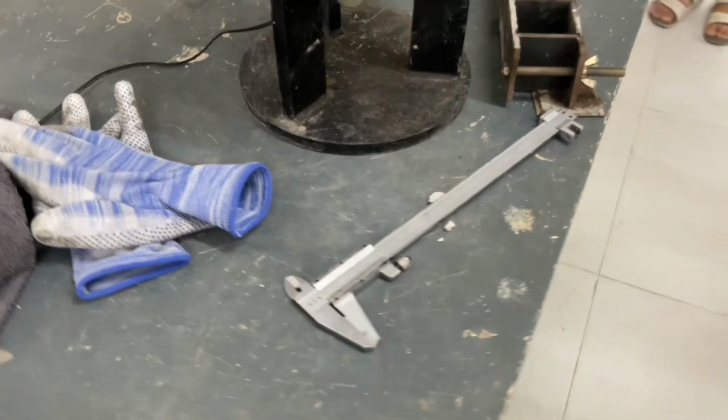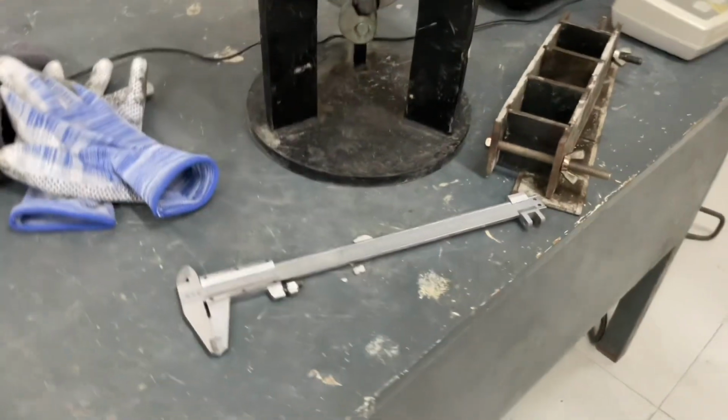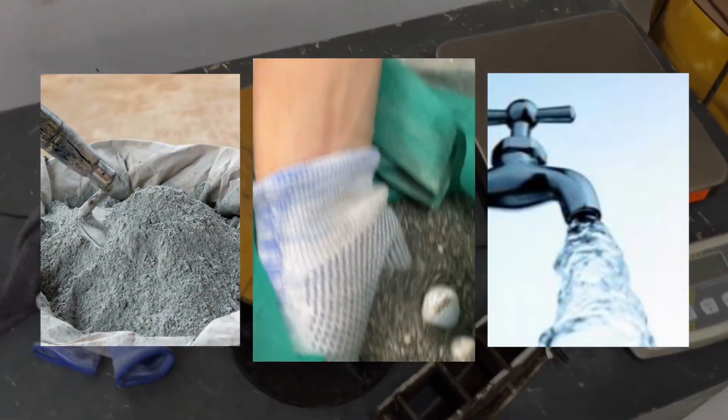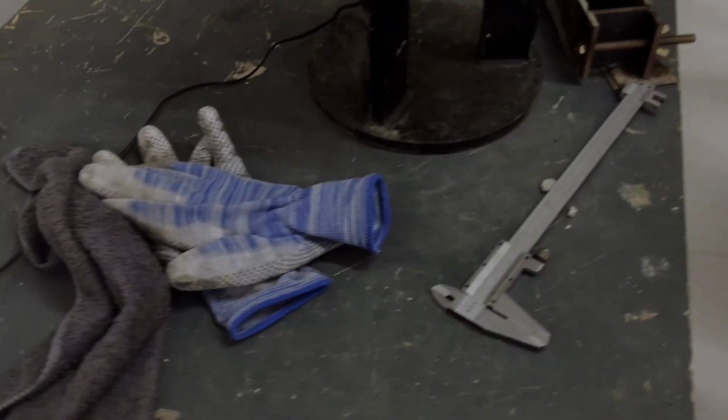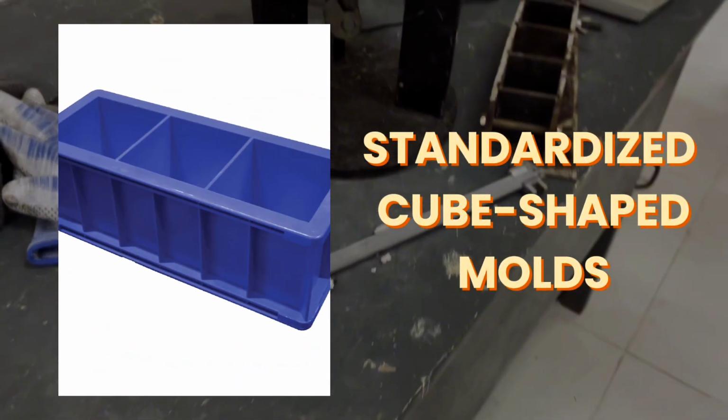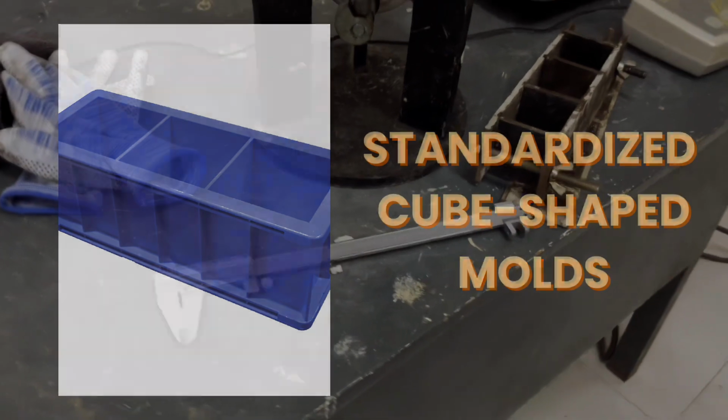Starting the experiment proper, first we gotta gather the things we need. That includes materials and equipment. For materials, we need cement, sand, and some water, which will all be measured as we go through the testing. For equipment, some standardized cube-shaped molds, which is typically 50mm cubed, to cast the mortar specimens.